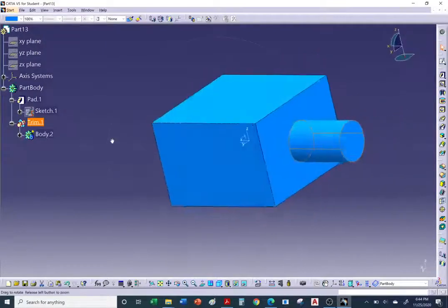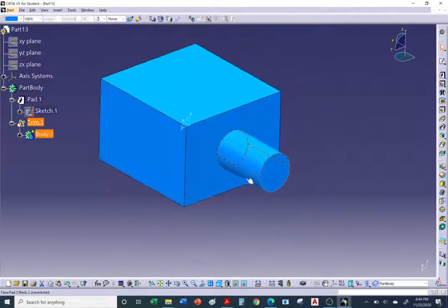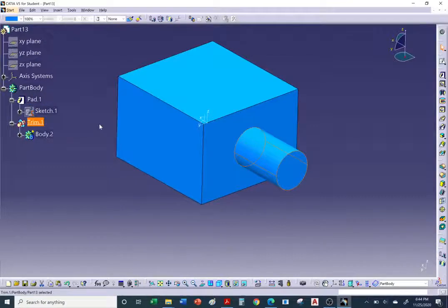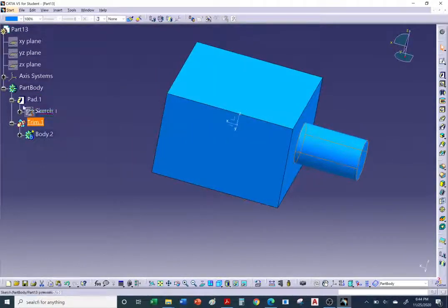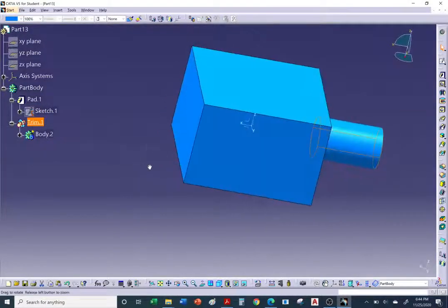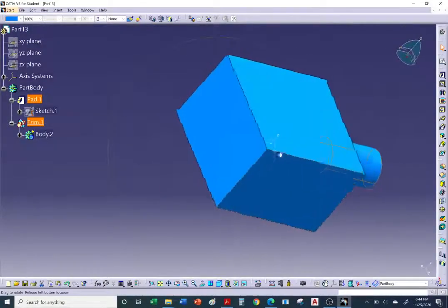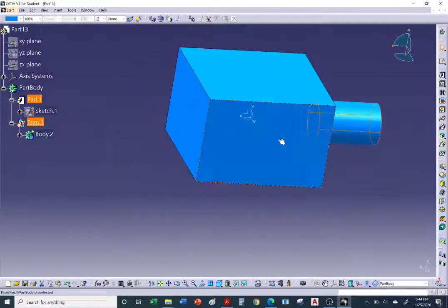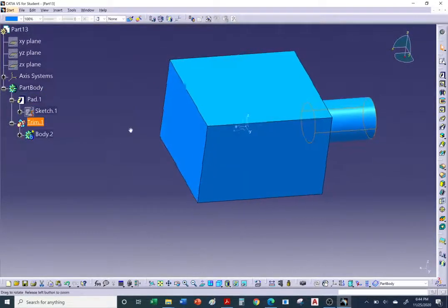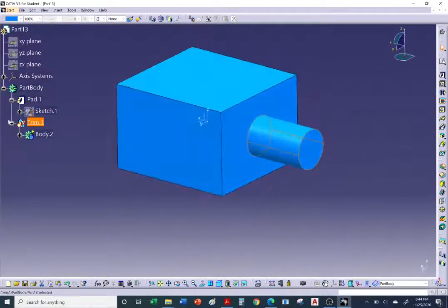And there it is. I do want to caution you that with union trims, if things change, if you change your sketch or you change the size of the part body, the union trim sometimes has trouble updating. So you have to go in there and troubleshoot and reselect, like a face, for example, to remove. Just be aware of that.